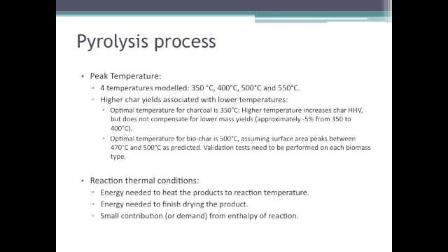So you discussed the preferred temperature, and for charcoal you said the lowest temperature because you get the highest yield, which I would agree with. And for biochar you said 500 would be optimal, assuming that this is where we get the best properties. Yeah. One of the things you didn't mention, which could have an impact on this, although it might give you the same answer, is the fixed carbon content. Because biochar is meant to fix carbon. Yeah. It is meant to be a climate change tool or whatever.